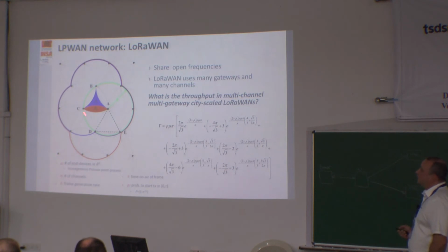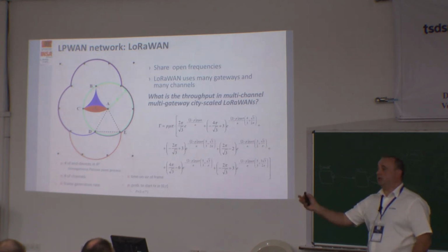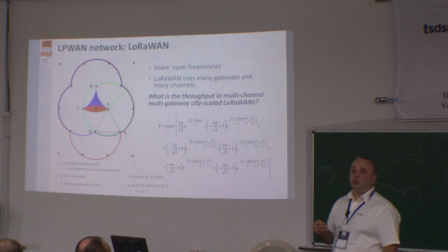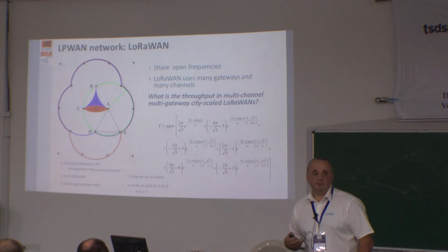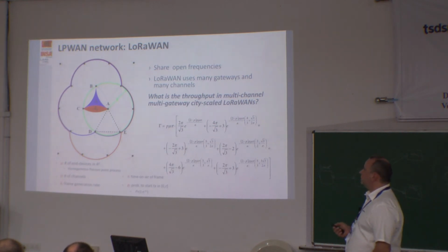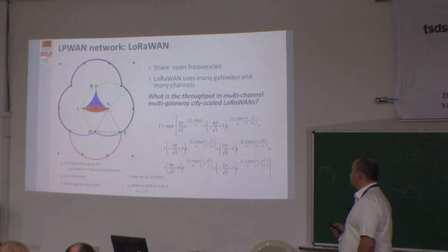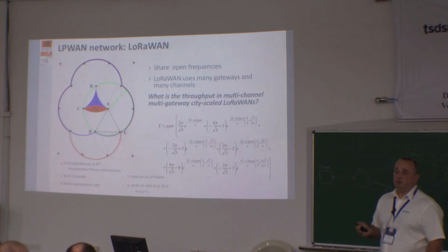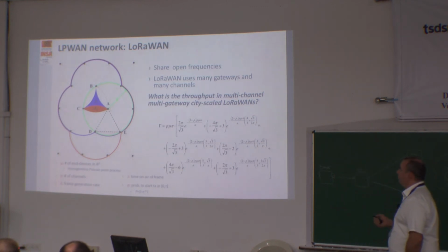And when you have several gateways, several or many devices, there is some conflict because it's a network where you push data, you try to communicate, and you don't know if it happened correctly or not. So when the density of devices becomes too heavy, because it's LoRa protocols, in fact, you can transmit on the air. So we made some estimation of the throughput depending on the density of devices, and to have also localization.